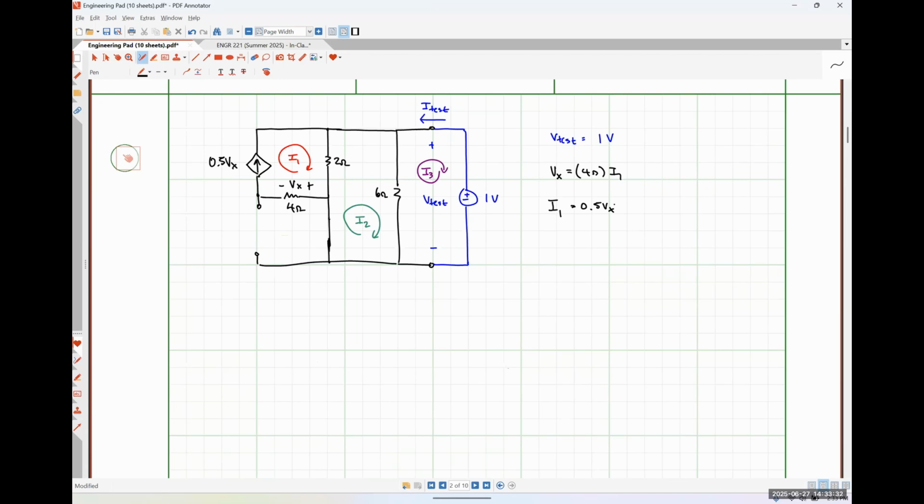We'll wind up rearranging one of these guys here in a moment because those guys have very similar information, so we can just come up with one equation from them. But before we do that, our KVL equation around mesh 2 is going to look like 2 ohms times (I2 minus I1) plus 6 ohms times (I2 minus I3) is equal to 0.